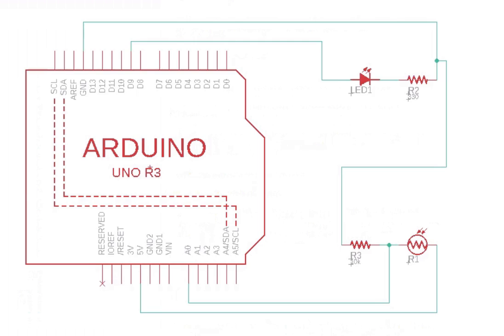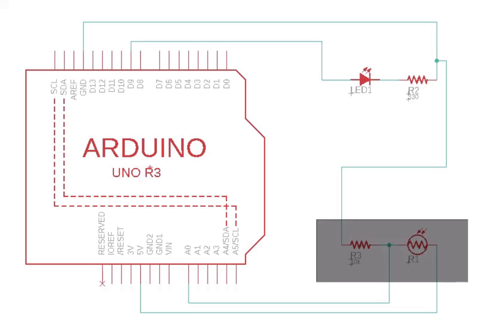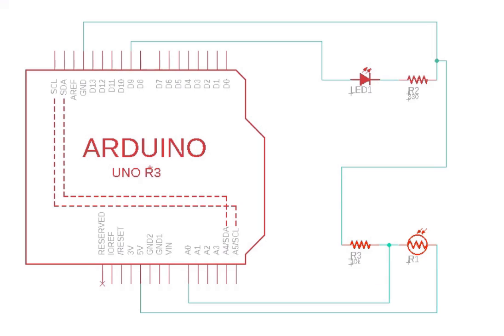So if we go back to the schematic here, the printer's error basically switches the position of the photoresistor and the standard resistor, so that instead of the photoresistor being connected to 5 volts and the standard resistor being connected to ground, it's the other way around. And having it hooked up that way is something worth taking a look at. So let's just very quickly wire it up the other way around.